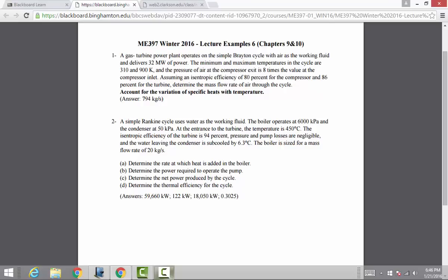So now, when you see the flow rate, you should be suspicious. You should see, okay, I have the mass flow rate, so I have a link between all those little parameters, little h, little u, little v, and rates and powers, like capital Q dot, which is the rate of heat going out, in kilowatts, or W dot, all this.